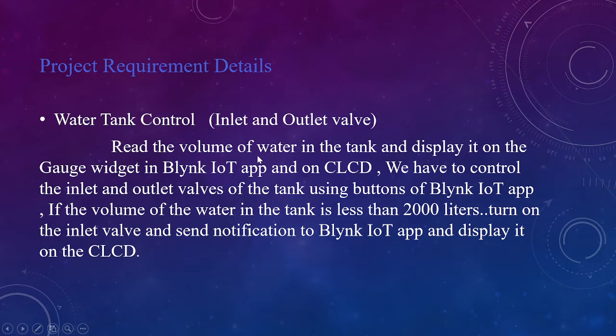The full capacity of this water tank is 3000 liters. When the water in the tank is less than 2000 liters, automatically turn on the inlet valve and send a notification to the Blynk IoT app and display it on the CLCD too.